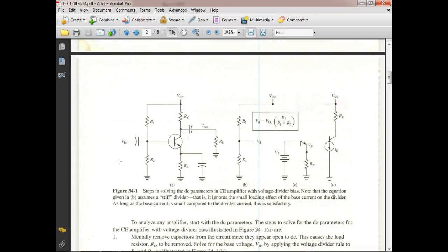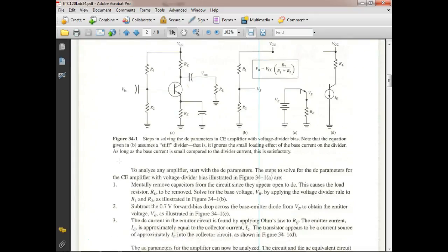So we had two people in the class say you put the black lead on the anode, you put the red lead on the cathode, the meter measures overload, and they just stopped right there. Well, if I hold two things in the air, it's going to measure what? It's going to measure overload. It's not going to identify a cathode. This could be anything. The thing could actually be bad. We had two people answer that.